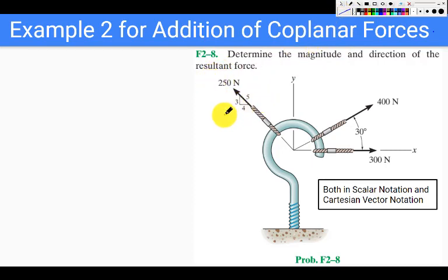So this force I can write as 250 times 4/5 I hat, sorry, 4/5 has to be I hat, plus 250 times 3/5 j hat. Okay, so this is the resolution of this force into its x and y components.